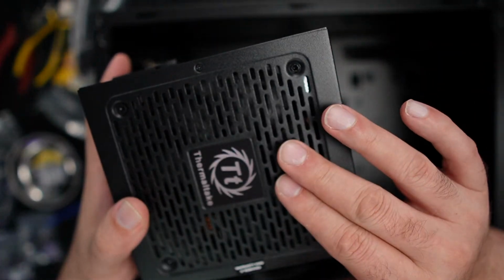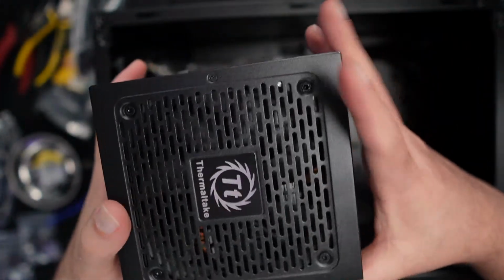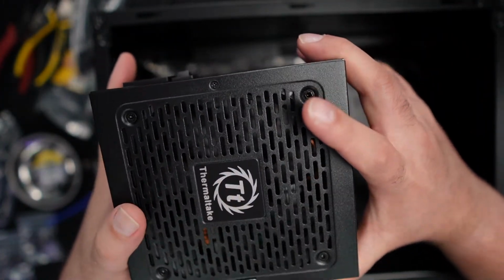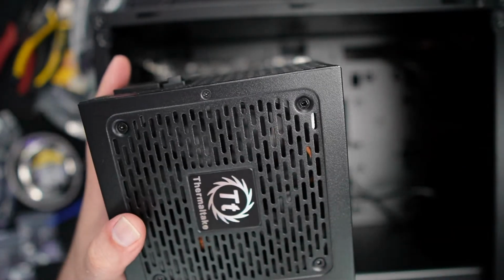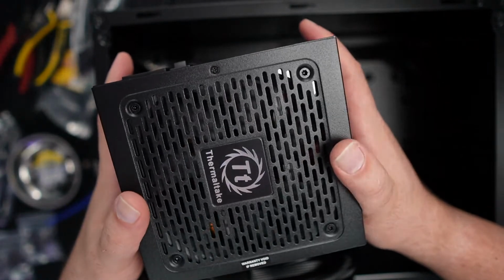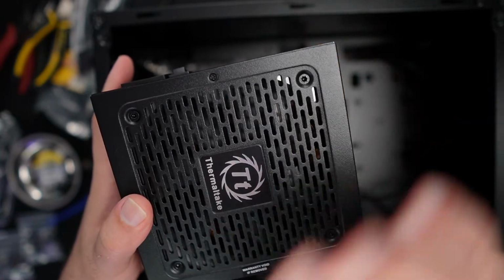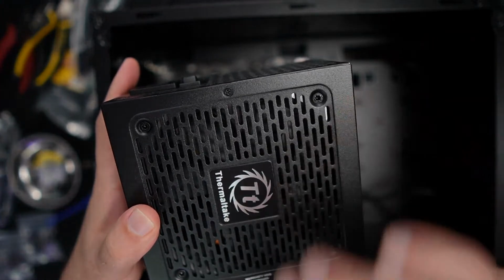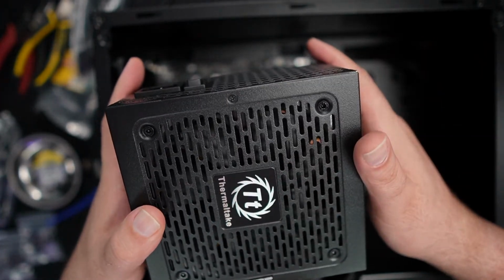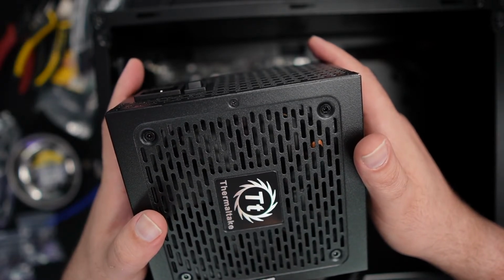This has a fan on it. The fan's on the bottom. I'm going to have this fan facing the bottom because we have a two-compartment case on this one, so there's an intake from the bottom. I like that better because the temperatures are handled a little bit better. It won't put the heat directly into the system. It'll take cold, fresh air directly into the power supply and exhaust it right out through the back, not going through the whole system. So it does add a little better protection against other problems.